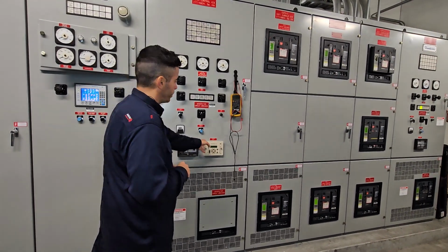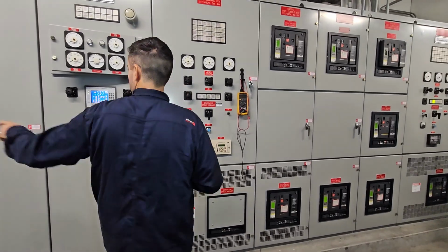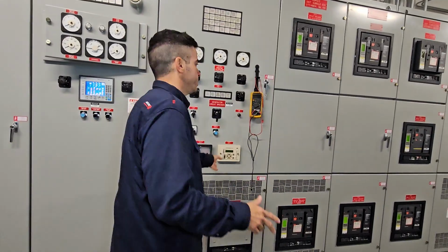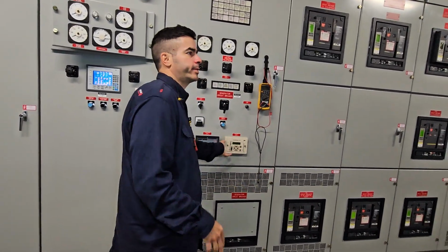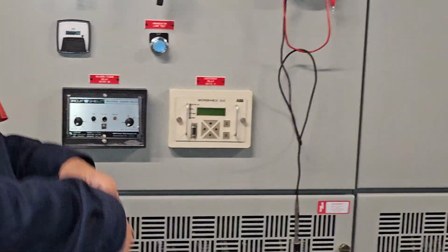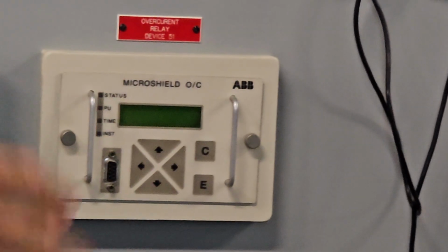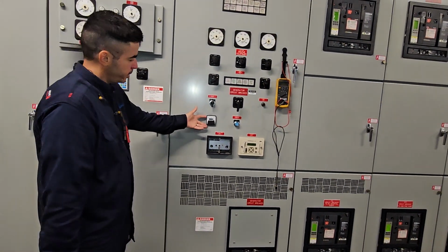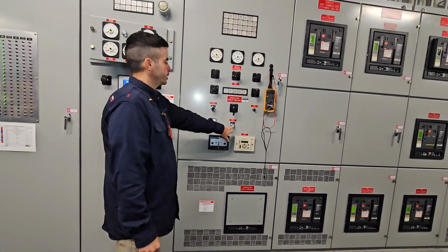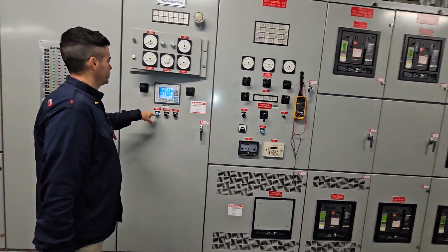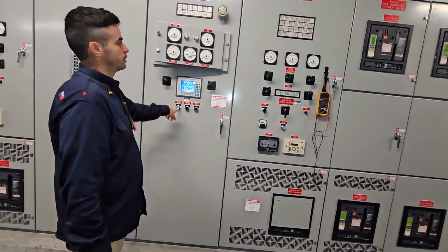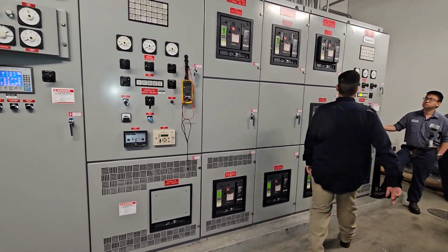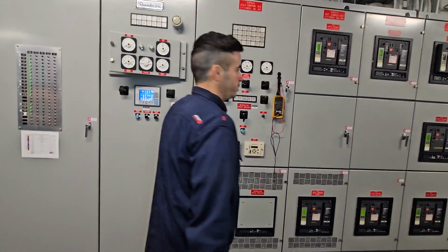And then we have an overcurrent protection relay. We only have this one in generator 2. We don't have that one in generator 1. But it's basically, as the name says, overcurrent. If we have a super high current, it will trip the breaker and it will shut off the generator. Okay? This is just the hours meter, and then we have a test button for the lamp test. All right, that's the safest button you can press. Questions so far?